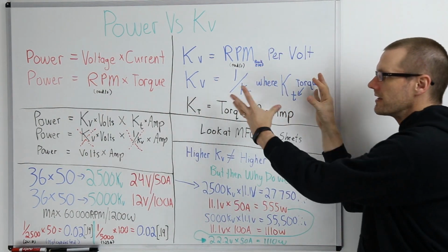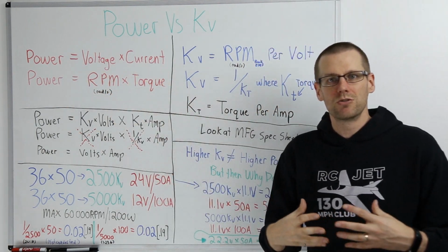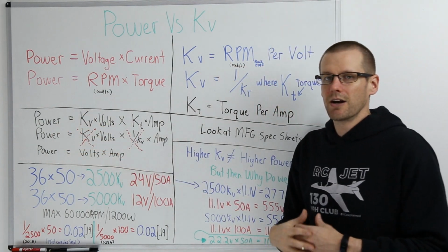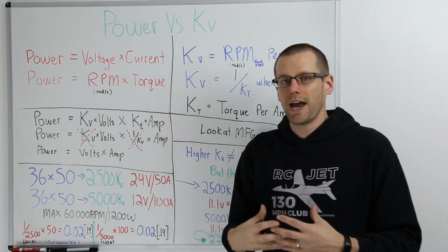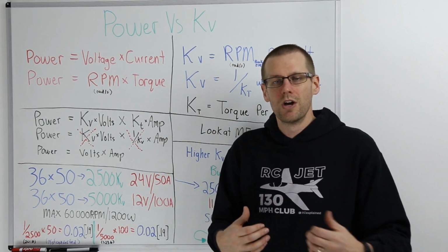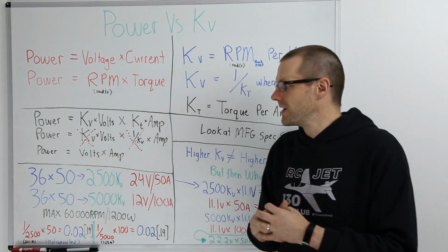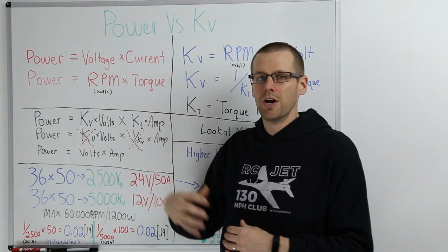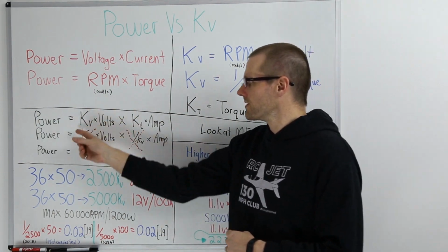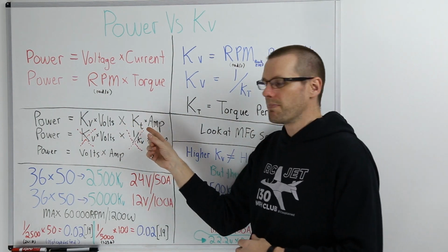So now if we take everything that we've learned and we throw it back into this equation of power as it relates to the mechanical world, we plug in power is equal to, and we know that RPM, when we're looking at our brushless systems, is the kV value, let's say it's 2200, multiplied by the voltage we plan to run, maybe it's 22.2, and then we know approximately what kind of RPM we expect to get unloaded from that motor system. So we simply plug that formula in here, kV multiplied by volts.